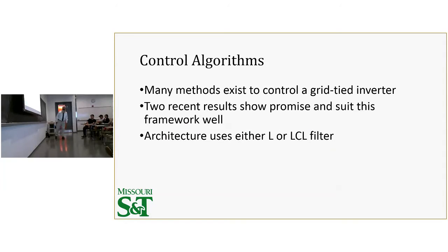All right. So let me move on from there to some control algorithms that we've been working on lately. I'll first say that there's plenty of methods in the literature for controlling a grid-tied inverter. But there's a couple I've been looking at that fit in this real well, and I've been able to implement using the multiple reference frame. And we can use either an inductor to connect to the grid or an LCL filter for a grid tie.